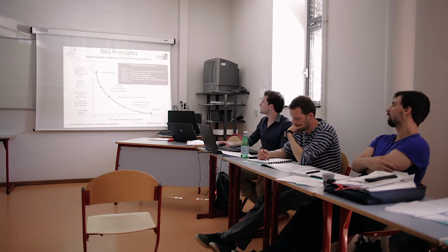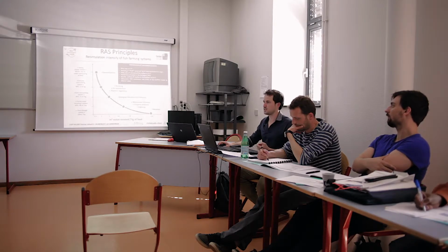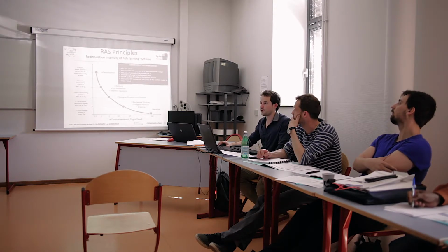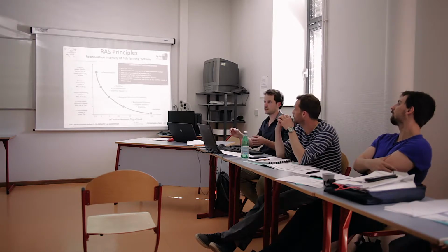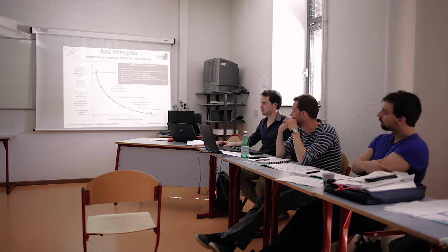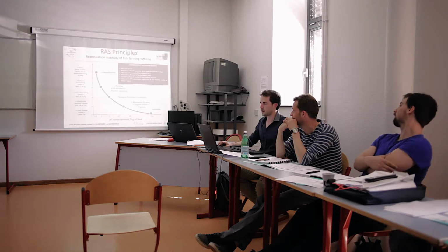The characteristics that define a recirculating system are the flow rate, the amount of fresh water per kilo of feed. This is on the scheme. The daily rate of renewal in the system, so it's the percentage of the quantity of new water on the global volume of the water in the system. So it's a ratio. The dwell time of the water in the biological filter, which will be at least 5 minutes.